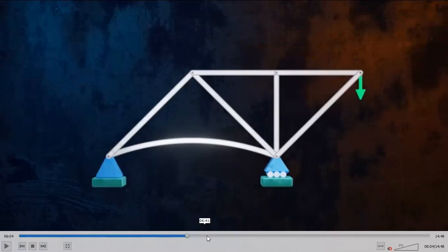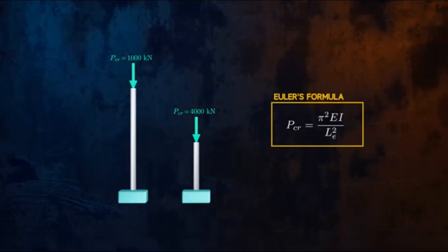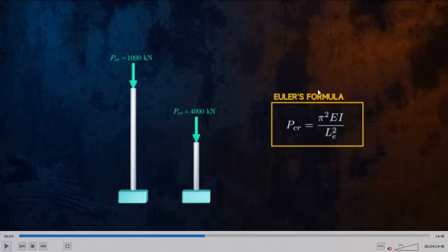That's another criterion you have to check. So you can see that when the length is low, your critical buckling value will increase. That means when the length is very small, it will reach infinity, right? So we can write something like this.